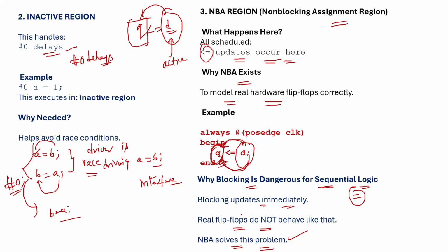Okay. So any blocking statements, they will execute immediately. Non-blocking statements will execute some other time. Okay. Monitor region means we need to use that $monitor, $strobe.